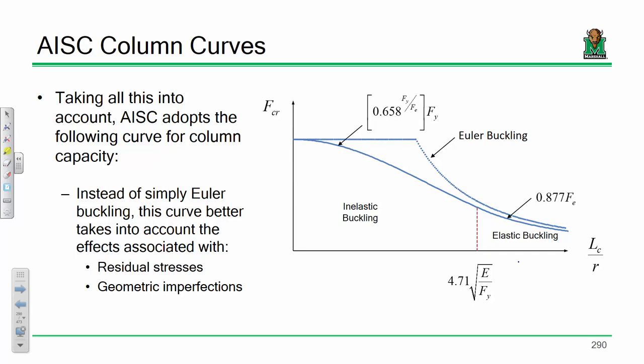Well, when you're erecting, let's take the new pharmacy building. That was a steel frame. If you think those columns were erected perfectly plumb, so the difference between plumbness and out of straightness. So here's a perfect column. An out of straight column would be like this. An out of plumb column would be leaned over. Okay? The code allows you some wiggle room for out of plumb, because you're not going to erect something that's perfectly plumb. But what you can do is erect a column that's within code limits.